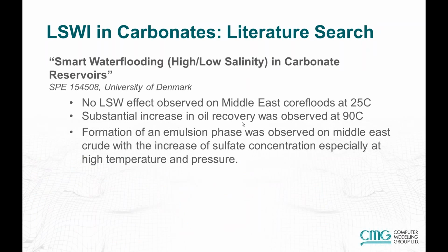Now this paper from the University of Denmark concluded that there is no effect observed on core floods at 25 degrees C, but at reservoir temperature, 90 degrees C, they saw a substantial increase in oil recovery. They also saw that the formation of an emulsion phase was observed with an increase in the sulfate concentration at high temperature and pressure. So that emulsion phase is normally associated with surfactant and IFT effects.